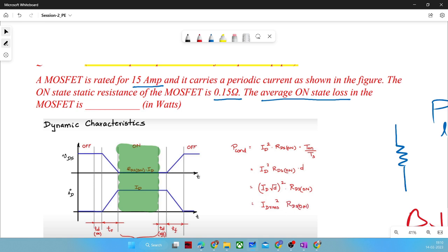That's the reason behind discussing all the majority and minority carrier devices. So MOSFET, generally, it can vary case to case, but generally MOSFET is modeled as a resistor because it is considered a majority carrier device, and IGBTs and BJTs are considered negative coefficient devices. So there you have to model it appropriately.